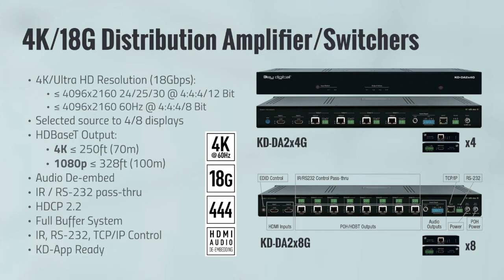These products support a full resolution up to 18 gigabits per second, meaning all of your 4K resolutions are covered, including 4:4:4 chroma subsampling up to 60 frames per second. Each of these products has two HDMI inputs, so the selected source is distributed to all 4 or 8 displays. It is not a 2x4 or 2x8 matrix. All 4 or 8 connected outputs will show the same thing at the same time.